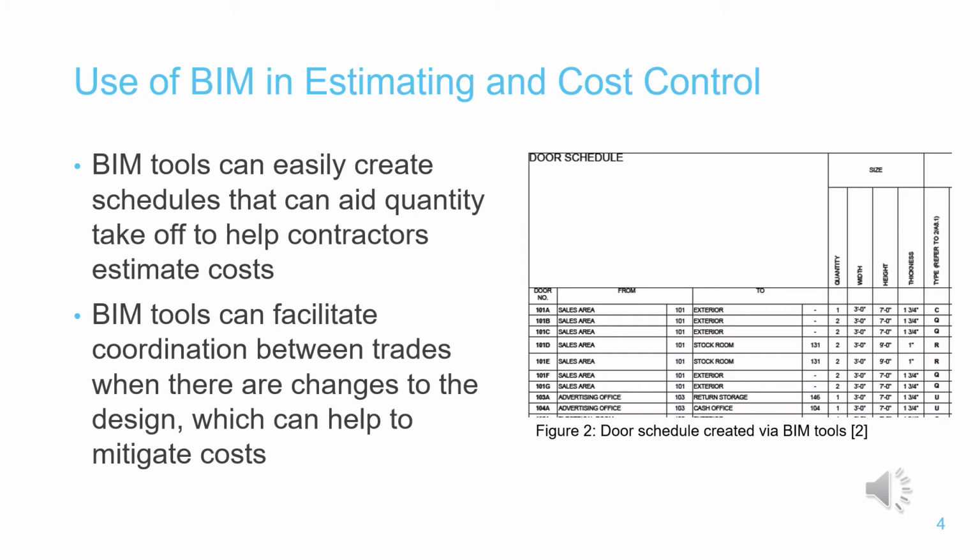With the use of BIM tools, the process of developing takeoff quantities becomes very simple. BIM tools are easily able to count objects and tabulate takeoff quantities into schedules like the one shown here. Bidders can then use these to estimate costs of constructing a project. With the bids that are received, the owner knows that each bidder has carried for the correct items and can easily compare the bids and choose the best one.